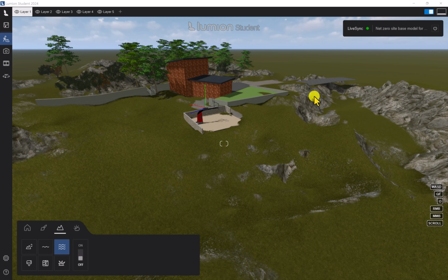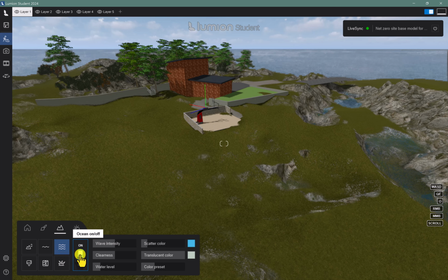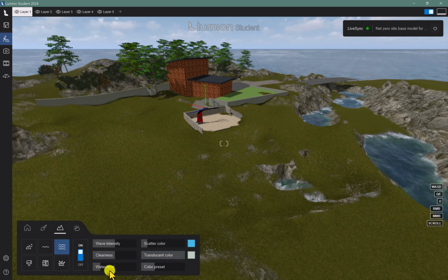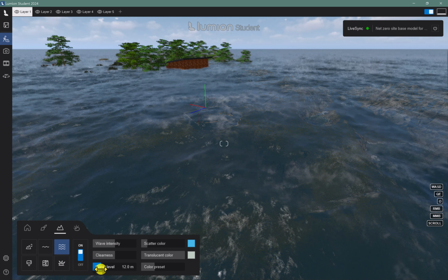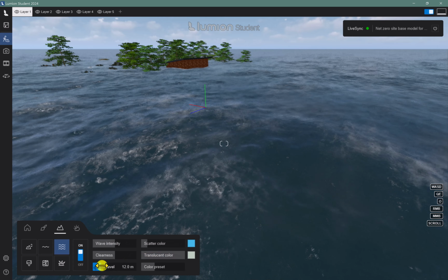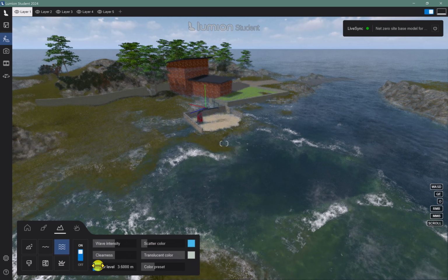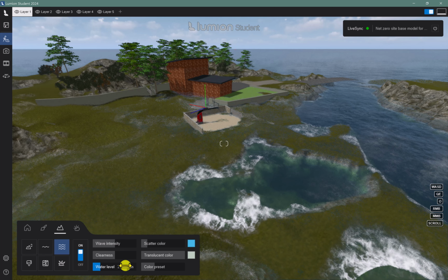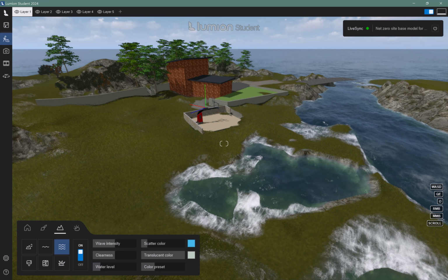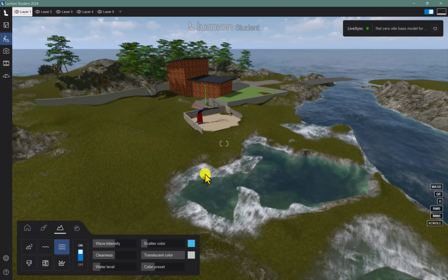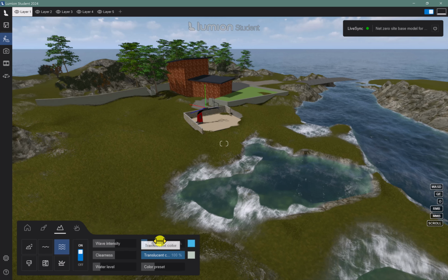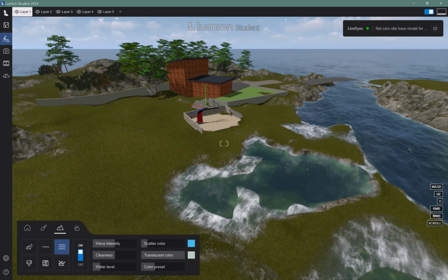Another fun feature that you can add here in Lumion is the ocean. So if you go here to the ocean tab and just turn it on, you can change the height of the ocean. Whoa, that's a lot of ocean rise there. You see how I can just drag it up. If you hold down Shift, it will move it a little more slowly. So obviously our site is not really that close to the ocean, but you can see that that's a pretty dramatic effect. Kind of a nice thing, and there's a number of features that you can control with the ocean.